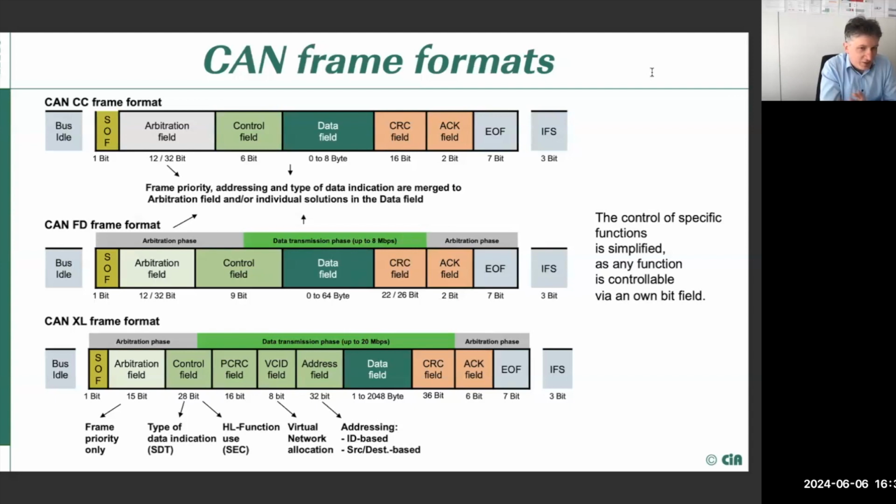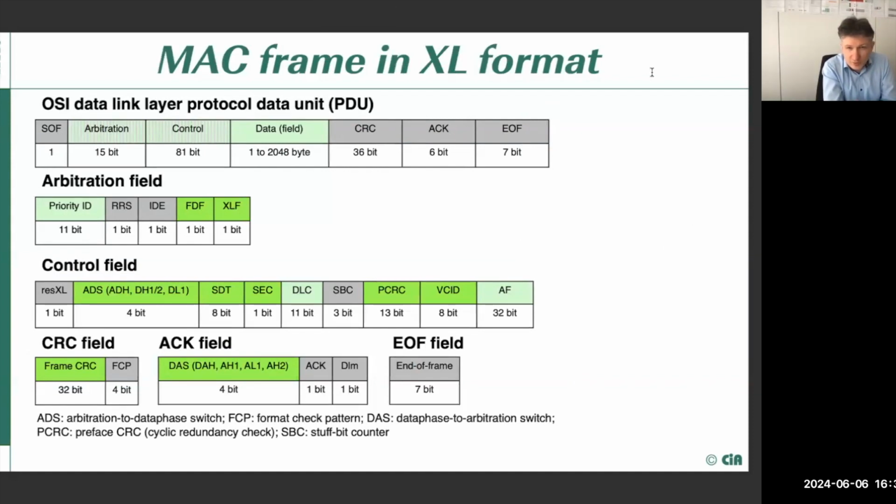Then we look into the frames themselves and see what has actually changed in comparison to the previous ones. We've talked about several fields that are new in CAN-XL. They have certain properties for higher layer protocols embedded into the frame itself. Every single bit in CAN-XL is also flexibly configurable. This is also new stuff in there. We take a look into details, into the bit fields inside. What is new in there? How do we handle them? What is different in CAN-XL? How does it help if you also have FD and classic CAN? So I'll briefly give an overview in here.